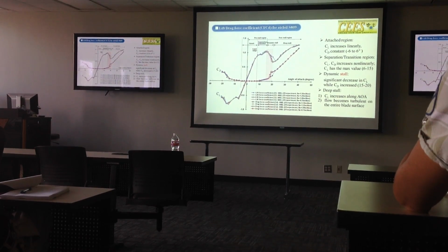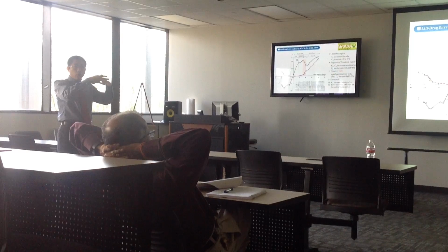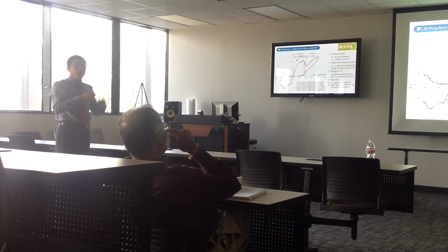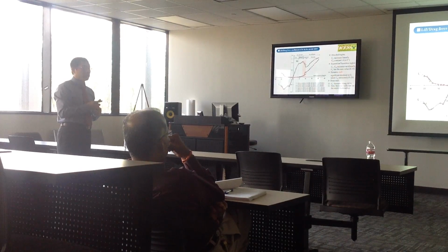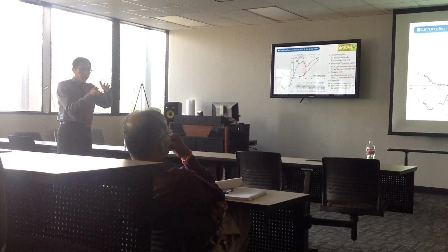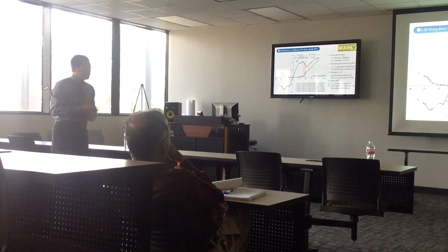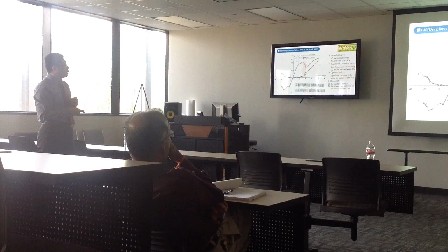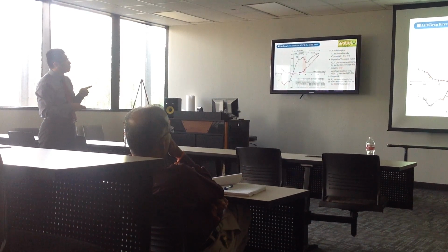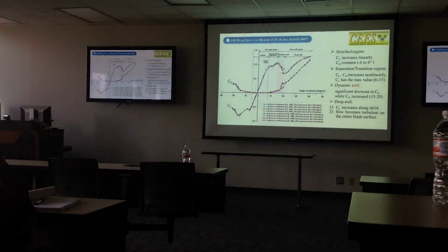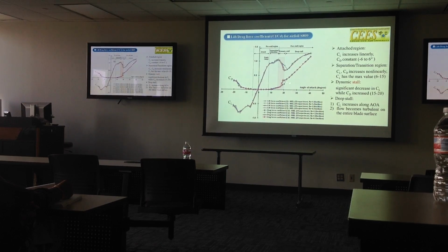As the angle of attack increases and achieves a certain angle, the stall will happen. Stall will vary based on the airfoil, the flow situation, and the Reynolds number. In our case, you can see the CL decreases from 15-degree angle of attack, so it starts the dynamic stall region.